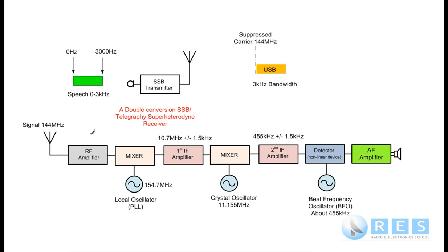Well, when the chap that's 2 kilometres away transmits, he's got such a strong signal that he overloads your receiver and it sounds distorted. And that happens because you've turned up your receiver gain so high to hear the overseas station. Then the overseas station stops speaking, it's the local operator's turn to talk, and your receiver is overloaded, and you have to adjust your receiver sensitivity to prevent that overload.